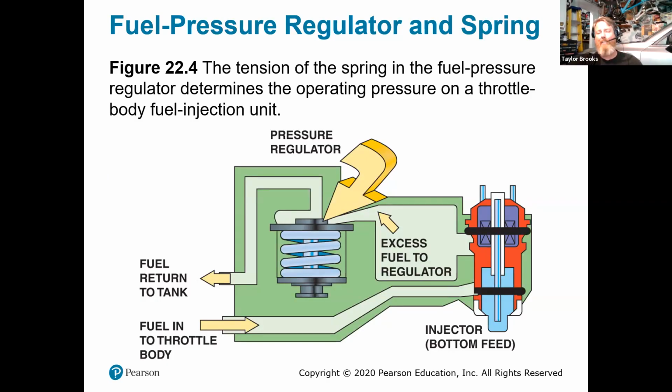And when pressure exceeds and overcomes the spring pressure of the poppet valve, it will push down and allow fuel to go past. Once that happens, however, that high pressure that was pressing down on the poppet valve is going to go to a low pressure area of either the return line or waiting to go into the fuel rail, and therefore the pressure will decrease right above the poppet valve, closing it back.